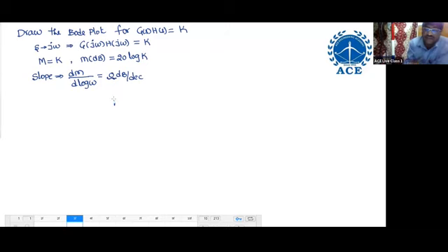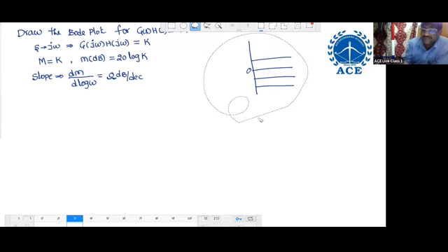But where is that straight line drawn? We can draw it at 0 dB, 20 dB, 40 dB, minus 20, minus 40. Where is that 0 dB per decade line? That is decided by K.